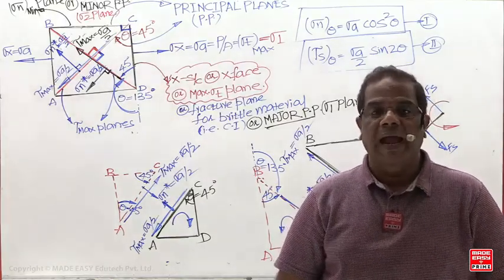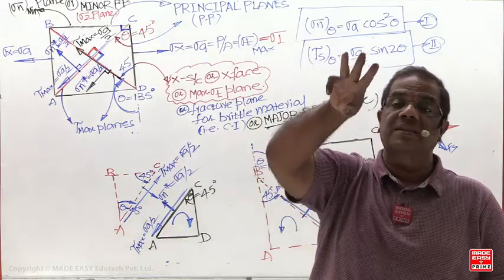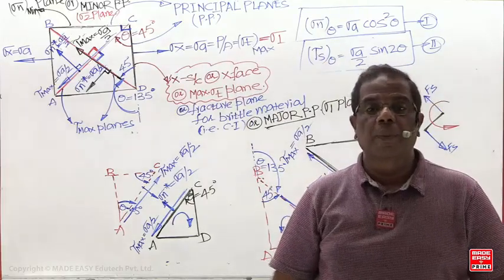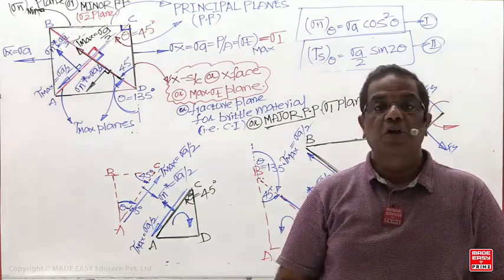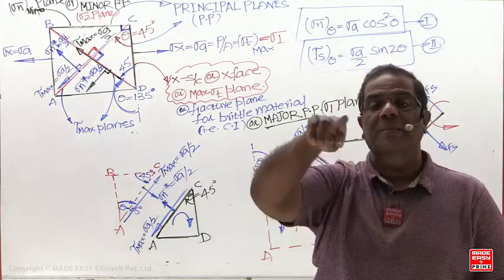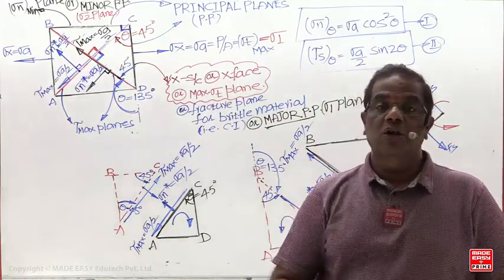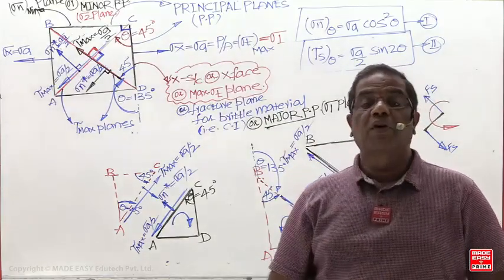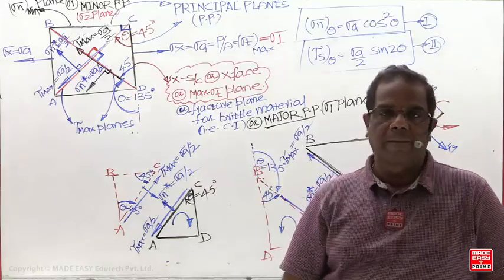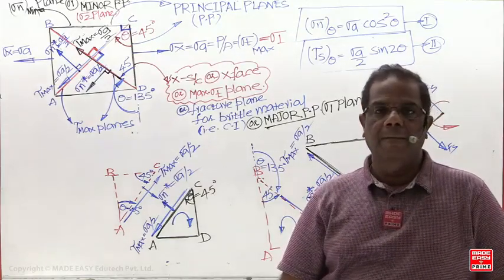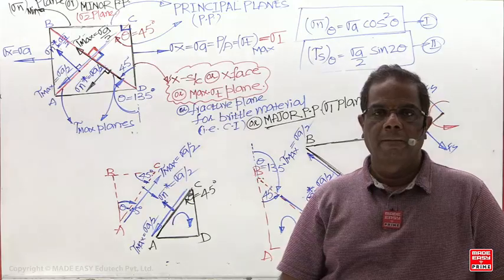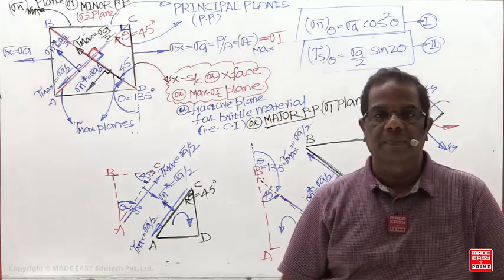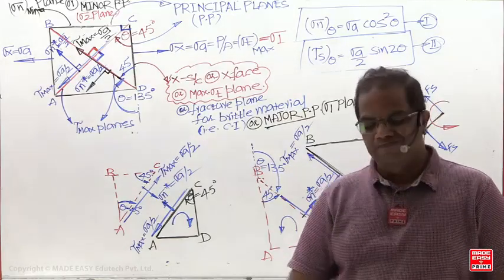Your syllabus is restricted to biaxial. So if somebody asks how many principal stresses there are, it is 3. But how many non-zero principal stresses? It is equal to the state of stress. Uniaxial state of stress, 1 is non-zero, meaning automatically the remaining 2 are 0. Biaxial means 2 are non-zero, sigma 1 and sigma 2, but sigma 3 is 0. But if you go for triaxial, there are 3 non-zero principal stresses, sigma 1, sigma 2, sigma 3.